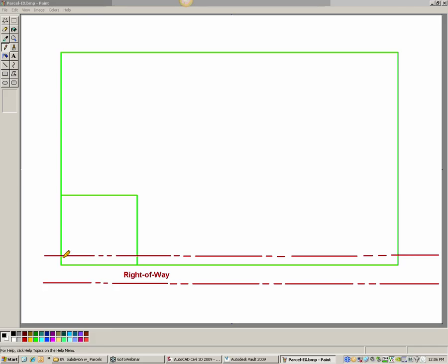Well, in an existing conditions plan, typically you show whatever shows on the deed. So if the existing lot goes out into the center of the road like this shows, that's how you need to plot it. And this right-of-way line on the north here, you would not have that as a part of the parcel, because if you would add that to the parcel, that would split this apart into different tracts. So you don't want to do that. Simply, you draw what I have here on the screen for your existing parcels: a parcel that goes out around, it's a big square, goes into the right-of-way, and then this north right-of-way line is just a simple polyline that goes right across the top, okay?